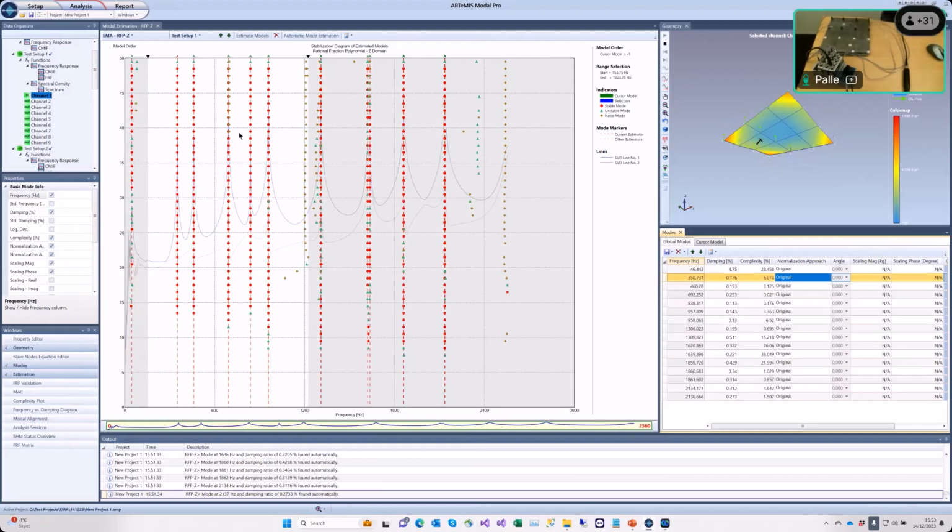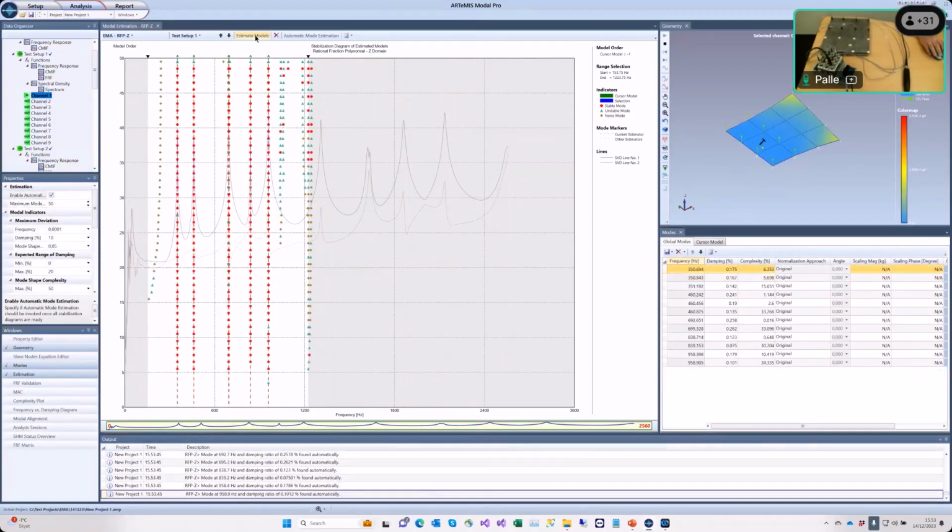We will regenerate, you could say, a new frequency axis in Z domain for this one here, and then work on this alone. And you can now see how it's only modes inside here that are being estimated. So in this way, you can zoom in on the parts of the FRF that you need to find modes for, and then leave everything out. There's no need to spend computational effort to estimate modes that you don't need. So this is the way you can operate this RFP-Z.